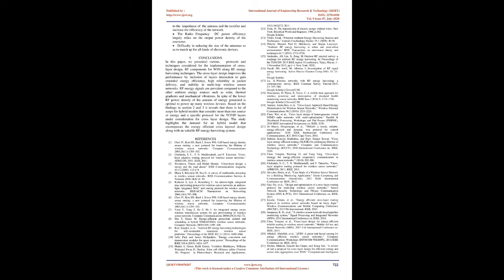Alipi et al. 2008 proposed a low-power maximum power point tracker, MPPT, circuit particularly to power up wireless sensor nodes and to store solar energy into rechargeable batteries even in unfavorable climatic conditions. The PCE is increased by using a modified ad hoc algorithm.